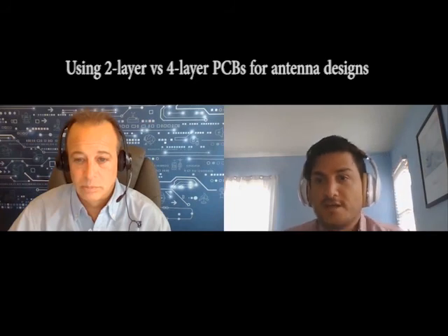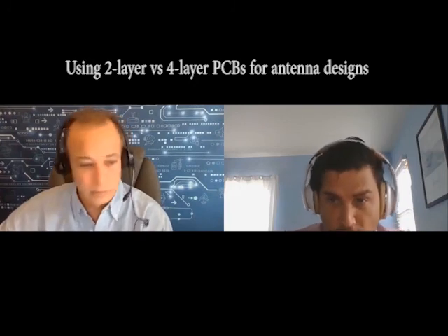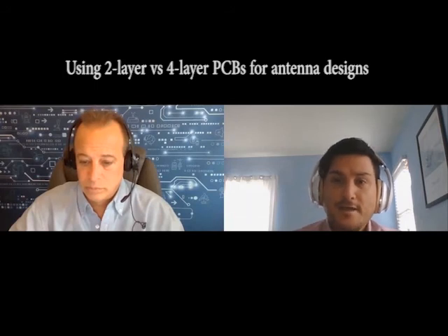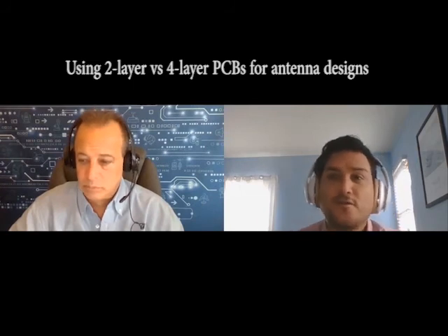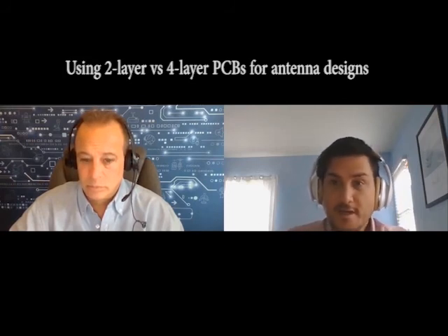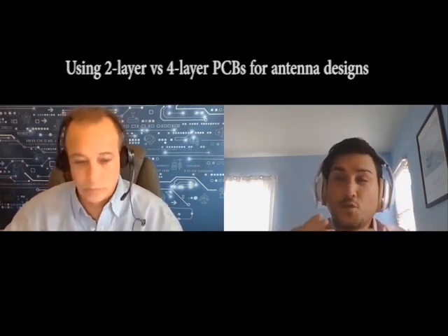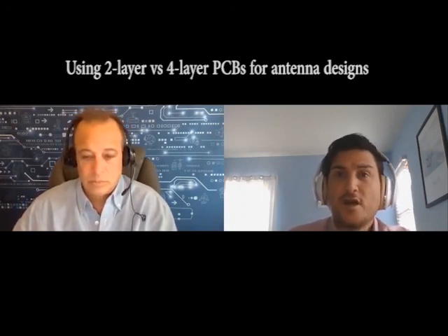So your resonating frequency was at 868, and 2-layer boards are usually just good enough to have pretty decent gain at 868, but in some really small form factor scenarios, it's actually best to use a 4-layer PCB, because those inner layers, electromagnetically speaking, expand what the antenna sees or counterpoises as a larger ground. So sometimes a really, really small 2-layer PCB might not be enough to have nice, decent gain. So it all depends on what kind of gain you're trying to achieve on a 2-layer board.